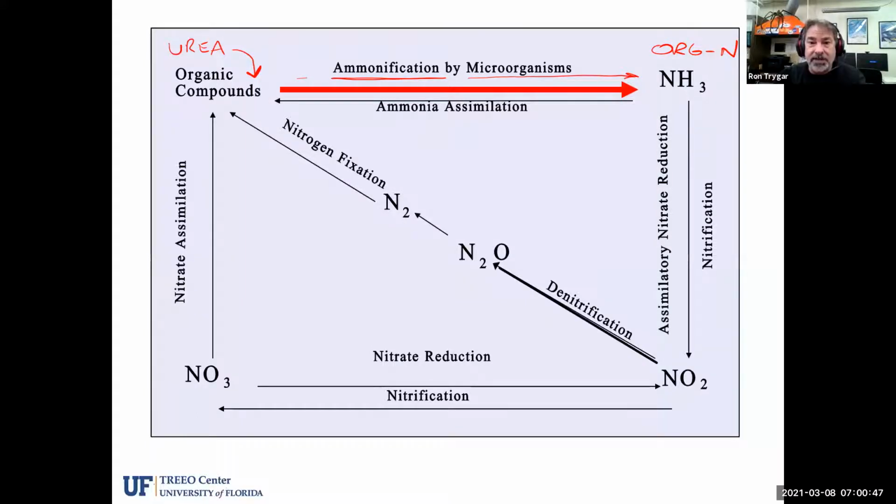So I want to keep bringing this up to you all to recognize that we don't just have ammonia coming into the treatment plant, we have ammonia and organic nitrogen. And that will end up being ammonified in the aeration tanks and potentially in your primary clarifiers if you have those. And that increases the load of the ammonia coming into the aeration tanks. So it's a forgotten form of nitrogen that I want to bring up to you that you want to pay attention to. Remember, this is not just a discussion to help you sit for an exam or study nitrogen removal for exam purposes. This is operational 101 stuff here.